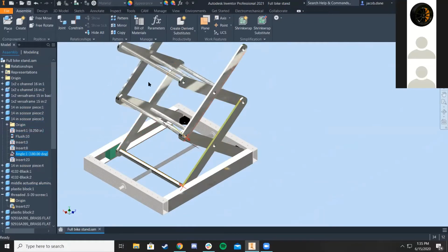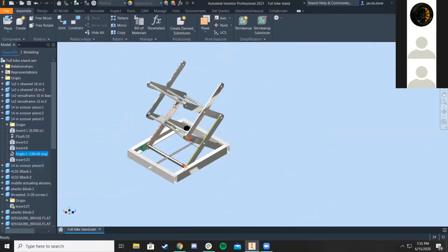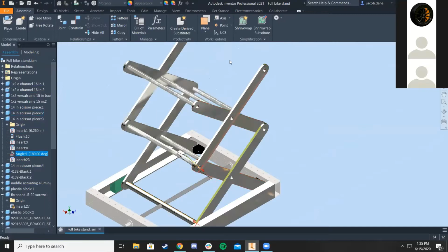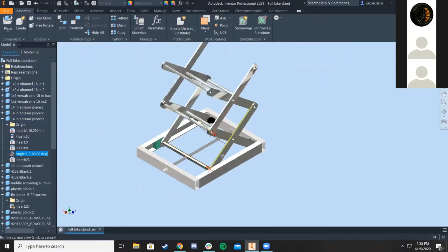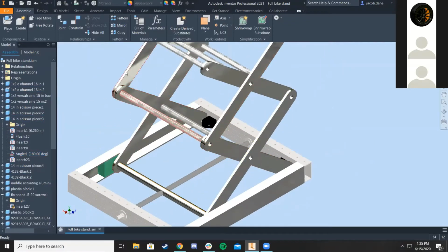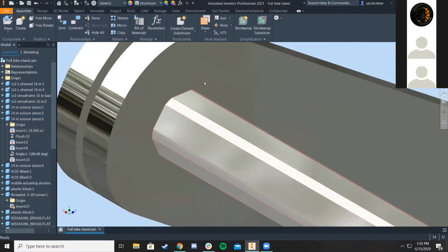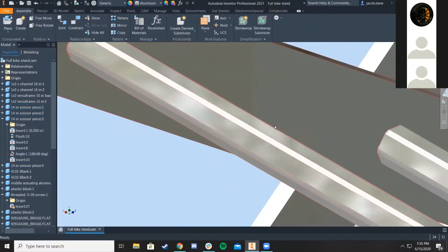And also he made these pieces flush, so that they're always flush with each other. That's the mentality of copying the constraints all the way through. And all these bars are just constrained with these holes and probably flush with these edges. Oh, they're hex, not just circular bars.